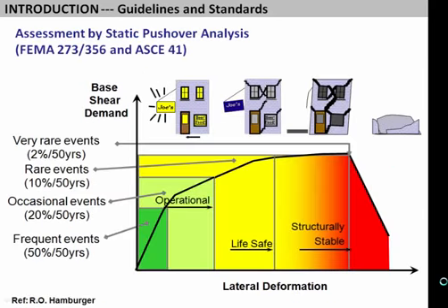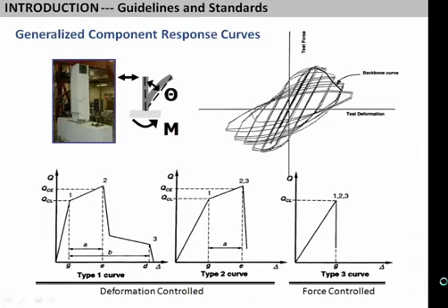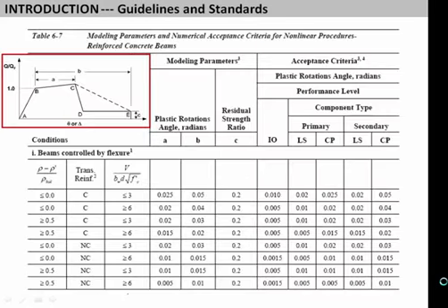But as Ron mentioned, it was really FEMA 273 introducing static pushover analysis apart from the performance framework that got some of the key essence of thinking about how you do nonlinear analysis for design into practice. That distinction between the elements that are so-called deformation controlled and force controlled, and the key thing there is the ones that are deformation controlled, those are the ones we have to model nonlinearly. Those that we choose to model elastic, by definition, will be force controlled, and their acceptance criteria determined accordingly.